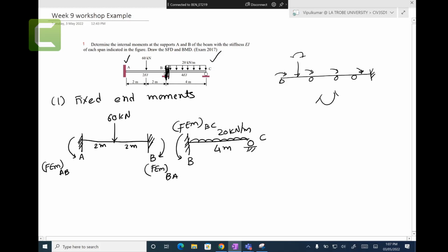So what we do, we transfer that equivalent load into the fixed end moments format. OK, so what we are doing here, the 60 kilonewtons goes on the left side and right side. We just distribute it to make the slope deflection method happy. All the displacement methods are in that sense. They don't like the load coming onto the members.